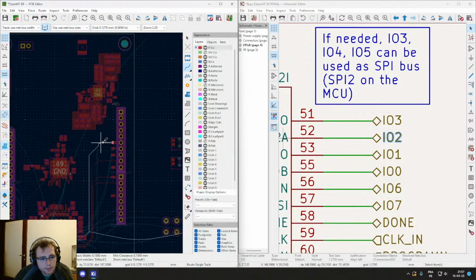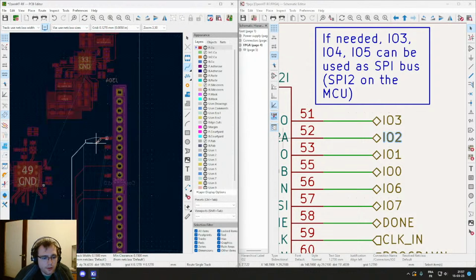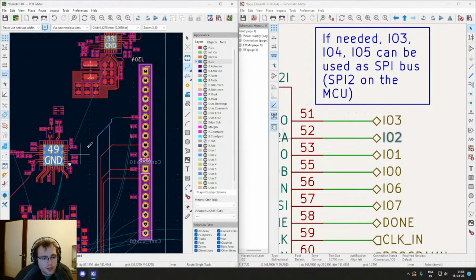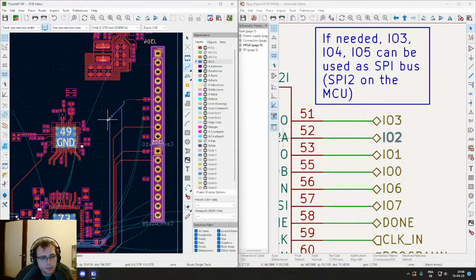In this case, sometimes you just want to avoid vias in your tracks too. And I try to route as much tracks on the top because it's gonna be just on top of the ground plane, which is gonna be very large, and this is for the return current of the signals that are carried on the lane.